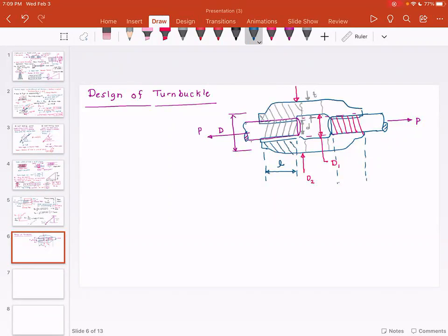But what we do is once we have these basic dimensions, to finalize the overall design, we expand upon these preliminary dimensions and then perform a finite element type of analysis at the component level and at the assembly level, just to make sure that the design is safe.